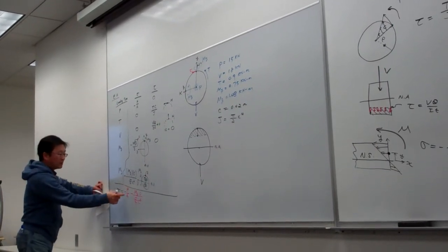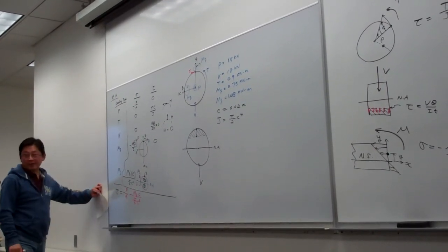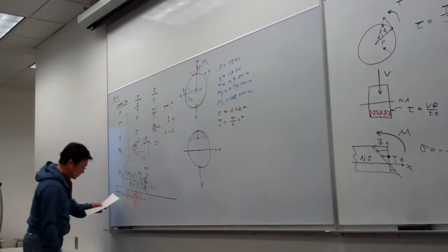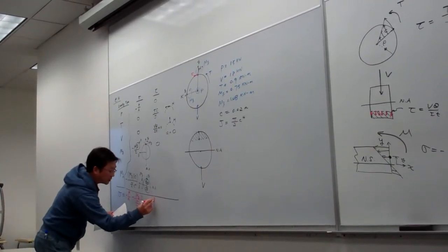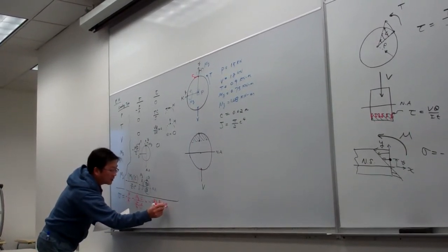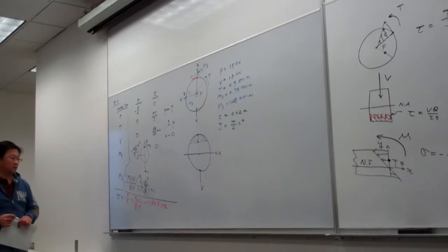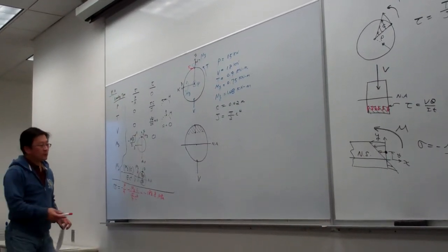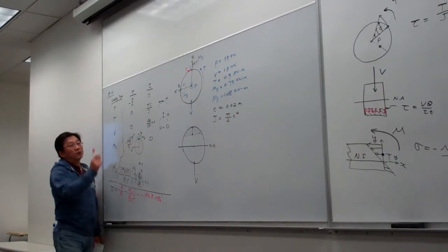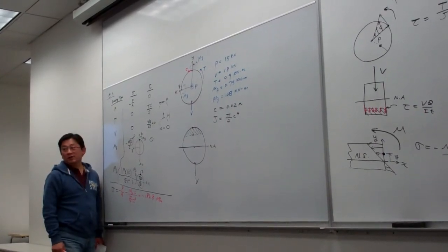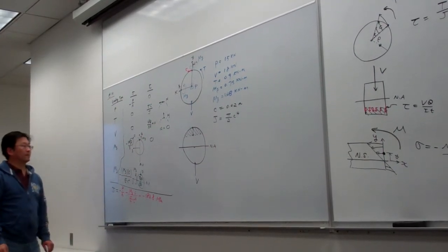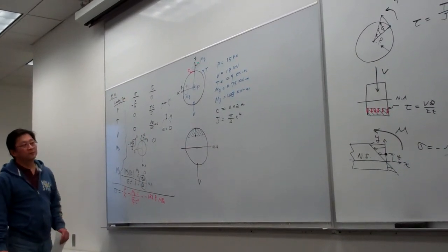And those ones, P, A, Mz, whatever, those are numbers, only magnitude. So we plug in here, that number is minus 183.8 MPa. And here, do your calculation carefully, okay? So that's the magnitude, and that minus sign tells us at point H that is in compression, in compressive normal stress. And this already accounts for sign convention too, right?